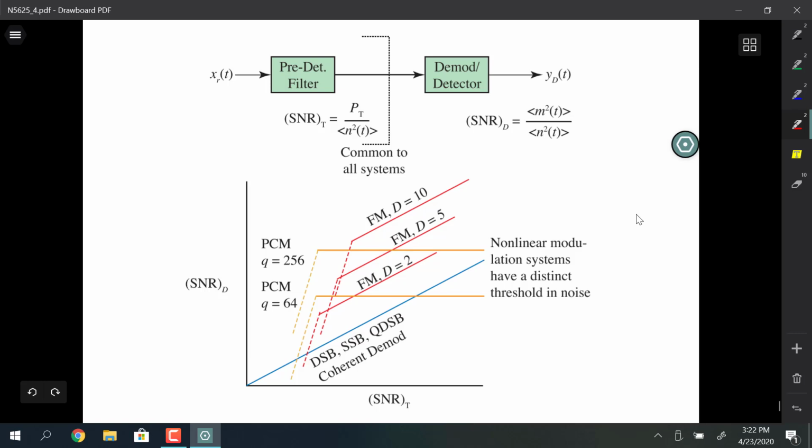So this is the general characteristic of all the modulations we've looked at so far, and I'll probably look at this again. As the signal-to-noise ratio at the input to our receiver, which is a more general measure than just signal-to-interference ratio, is below a certain level, like we have a lot of noise in the background because our signal is weak, double sideband, single sideband, and coherent demodulation,